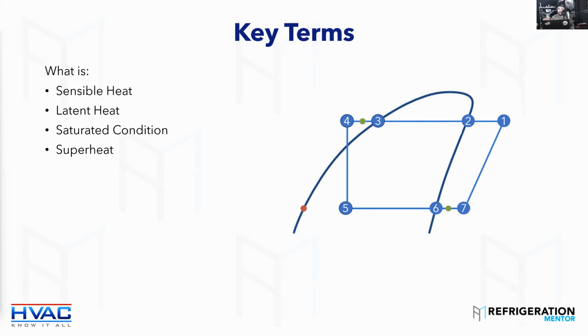But if we're talking about superheat in a practical sense, and we didn't see this chart, what is superheat relative to saturation? Both Brett and John said it in the chat: your pipe temperature over your saturated suction temperature. Yeah, exactly. So it's heat added above the boiling point.